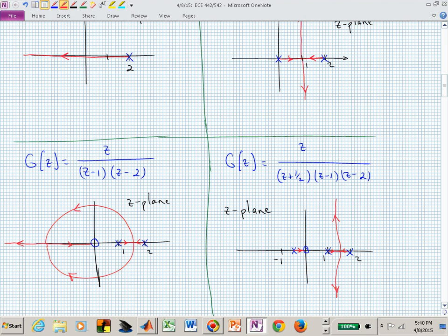They're going to meet. Maybe not exactly between, I didn't even calculate it, I just know they meet somewhere between. They go off, but in this case, because there's 2 poles on the right and a 0 in the center, once they break away, you can treat that as a radial distance and just draw a circle. If you didn't throw away your drafting compass, you can draw that circle. And then it just circles around and it re-enters that same radial distance on the left-hand side of that 0, and then one approaches the 0 as you crank up the gain. The other one goes off to the 0 at infinity.